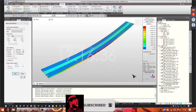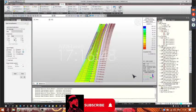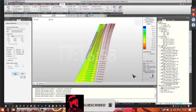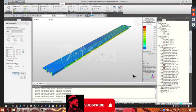We see that the deformed shape is coherent. We have, for example, the effect of wind load on one side. And for example, we can test the temperature, uniform temperature. You can see if the disposition of supports worked. And as we can see, we don't have bending moments due to the freedom of the bridge to expand.